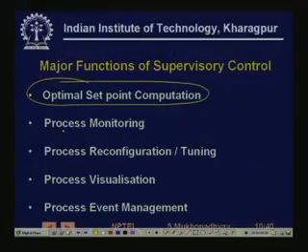So, all this is done by the supervisory control layer. Supervisory control always looks at the process and sees whether things are going fine. For example, breakout detection, as I was saying: by looking at the temperature profile and the mold levels, the system is always monitored such that we can detect the possibility of a breakout and then immediately take corrective action so that breakout does not occur. So, that would be like process monitoring.